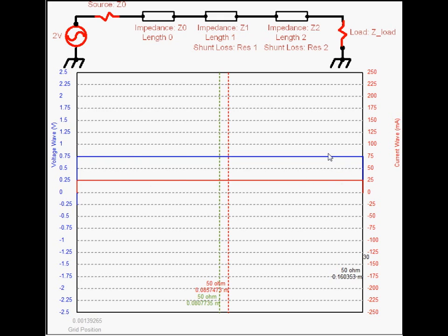Now, this voltage is what comes out when you have the 50 ohms and the 30 ohms. So you would have the 30 over the 80 times the 2 volts, so it's 0.75 volts. It's just a voltage divider in the steady state case. And the 25 milliamps is the 2 volts divided by the 50 plus 30, the 80 ohms. So that gives you the 25 milliamps in the steady state case.